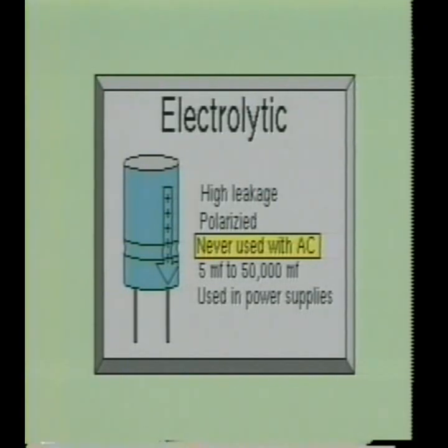These are normally polarized and should never be connected in a circuit backwards. If a polarized electrolytic is connected across a circuit with reversed polarity, the capacitor will become a good conductor. This will cause a high current flow, which develops heat in the capacitor. The heat will cause the electrolyte to boil, and the capacitor may explode.